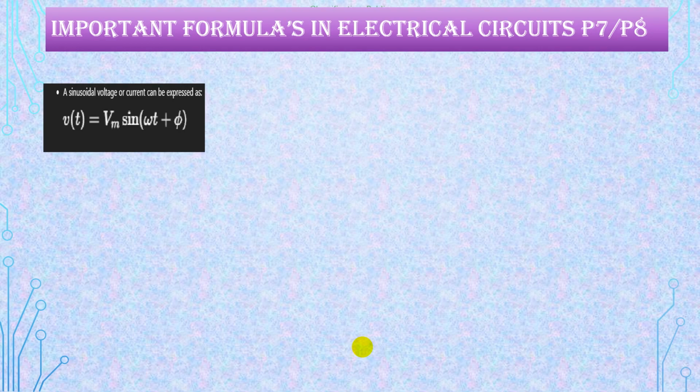For resistance, there is no delay. There is no integration and no derivation. Only for integration and derivation does the sign change: sine goes to cos, cos goes to sine, right? So nothing is there for the resistance, so it is in phase. For resistance, there won't be any lagging or leading. The phi will be 0 for voltage and current. This is called in phase.